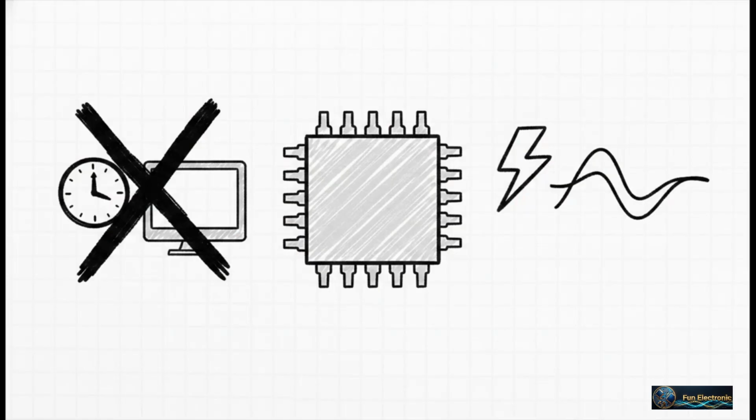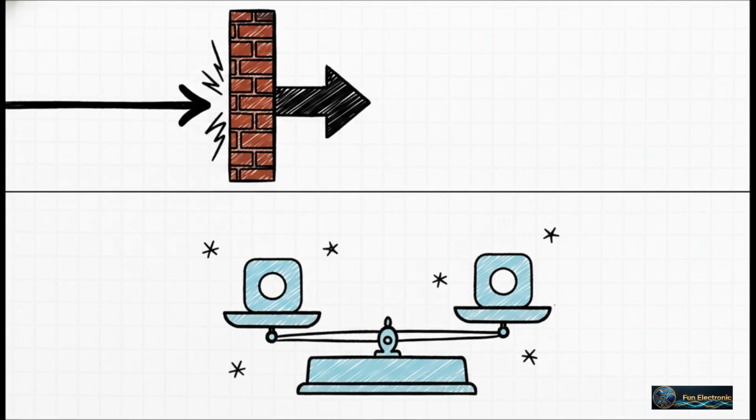Enter the difference amplifier. By using a basic operational amplifier chip, an op-amp, configured this way, we can subtract those two voltages instantly. There's no code, there's no clock cycles. It is just pure physics doing the heavy lifting and doing the math in real time. It's actually really cool. Now, before we actually build one, we've got to remember the two golden rules for op-amps